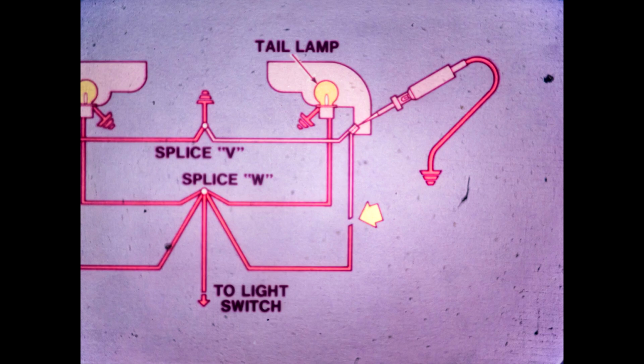Of course, if the test lamp does not light when you connect it between the side marker and ground, it tells you that there is a problem between the socket and splice W of the positive conductor.